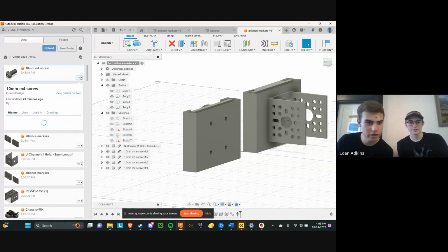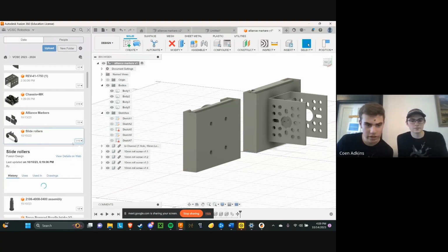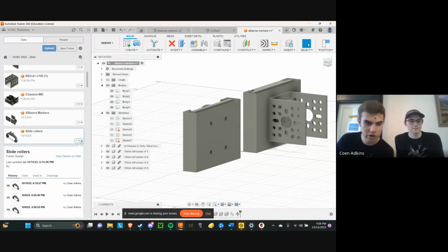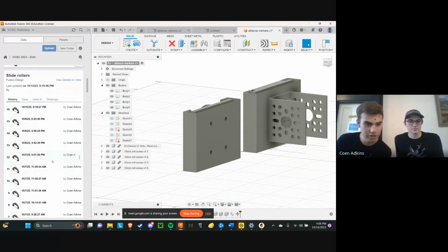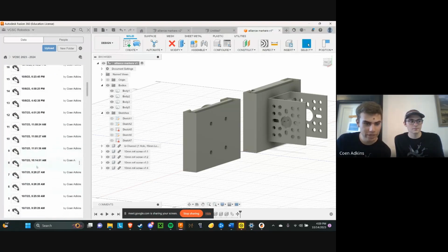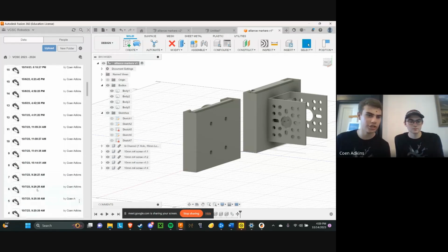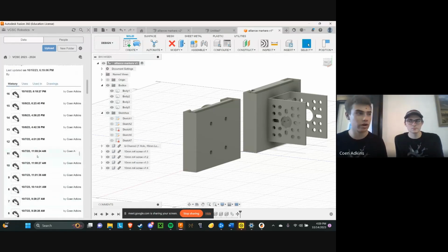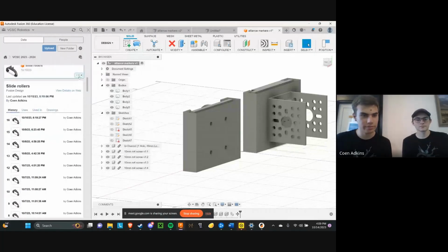Oh yeah. So in here, there's the version controls. We'll go to a part that we've messed with a little bit. In here, it says V16 in the corner, and it has a little drop down. And you can see here, it'll show all of the versions. Right here, it just shows separate times you've saved. But if there's a significant change that you made and you think, okay, that didn't work, or hey, I kind of liked that a little better, you can go back in the history and see where that was, and then make that your new design, like update it to that one.